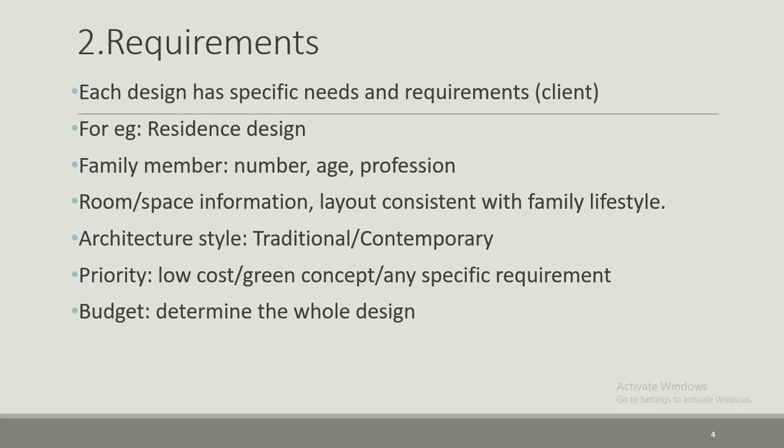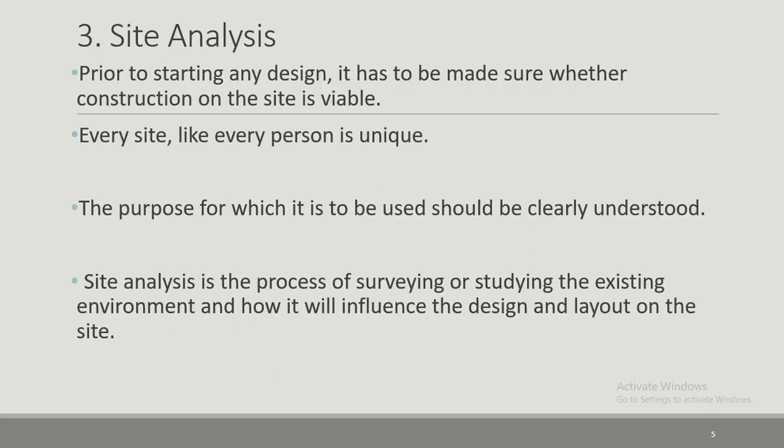For example, in residence design you need to know about family member, their number, age, and profession. Room and space information, layout consistent with family lifestyle. Architecture style, traditional or contemporary. Priority, low cost, green concept, or any specific requirement and budget, to determine the whole design.